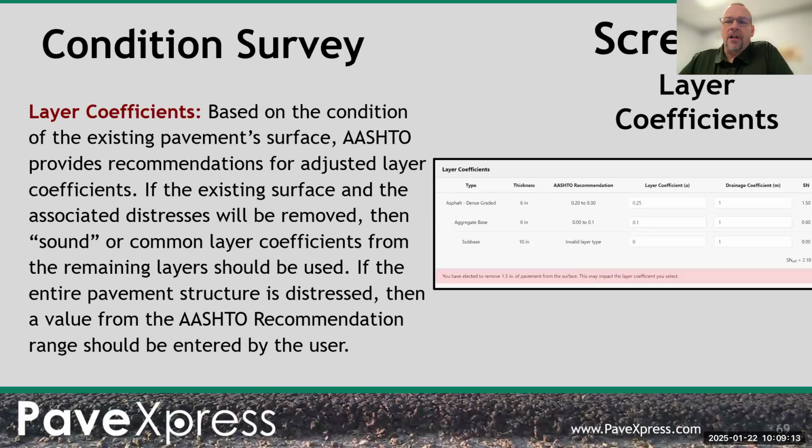It'll also give you warnings too. Say you did put in 16 feet of subbase. It'll probably give you a warning at the end that the structural number exceeds the required structural number, because your layer protection checks say your subbase is basically stronger than the pavement you're putting on top of.